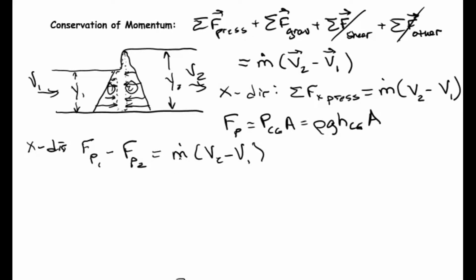We also need an m dot. If you remember the equation for m dot, well, that's just rho VA. All right, and we could put rho V1A1 or rho V2A2. Let's go with 1. And our area that we're talking about in both of these are our cross-sectional areas.